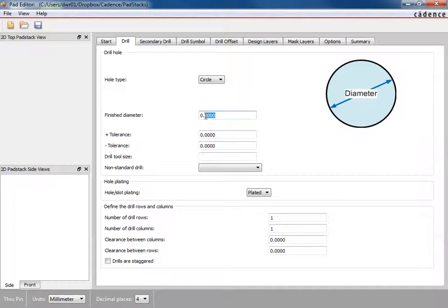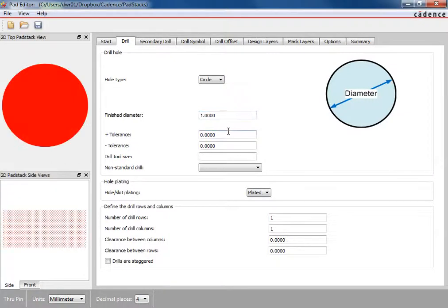That doesn't give you any room for tolerances on the size of those pins. At minimum, you would want a 0.9 millimeter hole, and quite frankly, for a 0.8 millimeter pin, you might actually just do a 1.0 millimeter hole. As far as the tolerance, we don't need to worry about this, and it will bring up our circle.